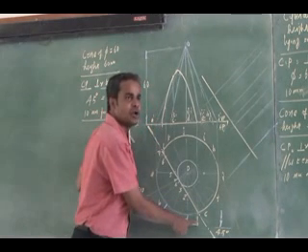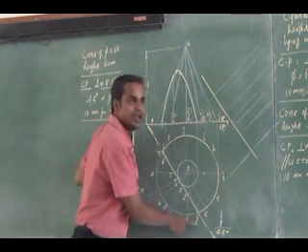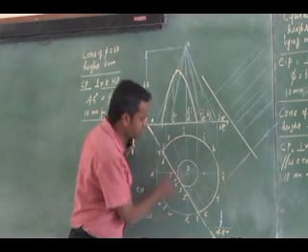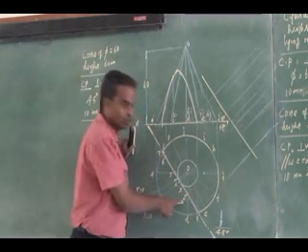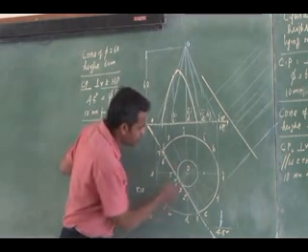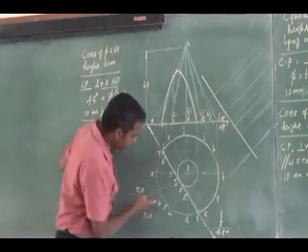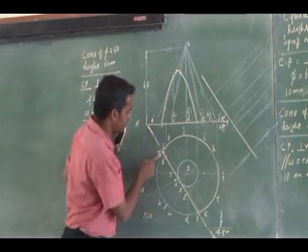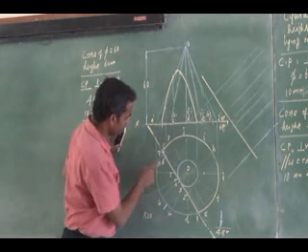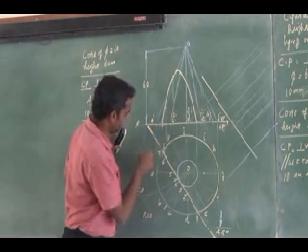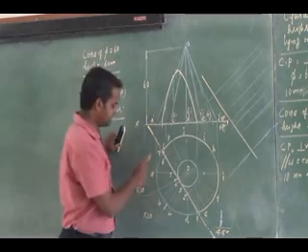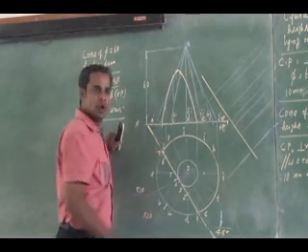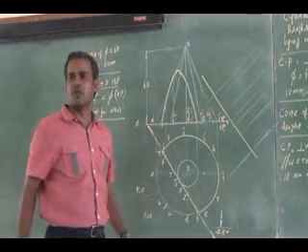Starting from here, I am rotating the cutting point. 1, it is on base. It cuts the circle, 1. Then it cuts the generator DO. That is cutting point 2. Then it cuts the generator CO, cutting point 3. Then it cuts BO, cutting point 4. AO 5, then LO 6, then it cuts again the base, that is 7. So totally 7 cutting points in the top view.